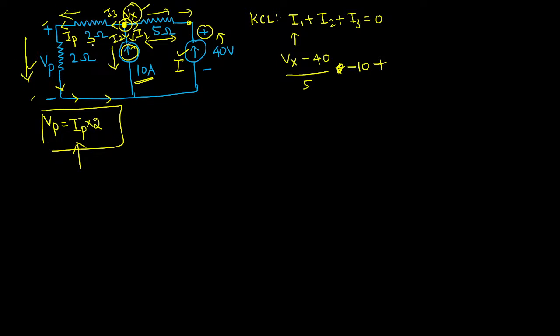What I will do is, you know this 3 ohm and 2 ohm are both connected in series only. So I take the total resistance as 5 ohm. And here we have 0 voltage, we know. Sir, here we have 3 ohm. Right now I am not focusing on that Vp, because my target is not that value. I have to find out the value of Vx.